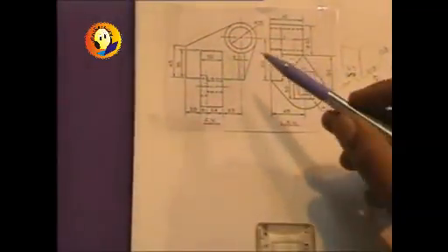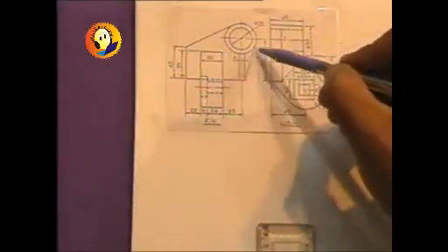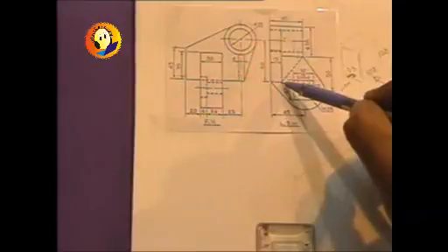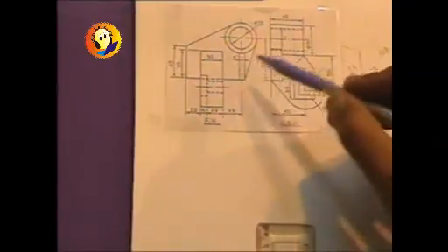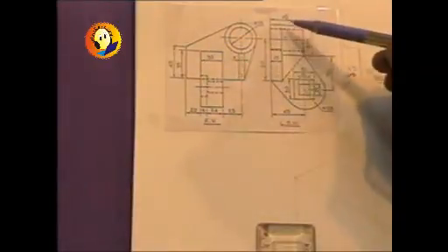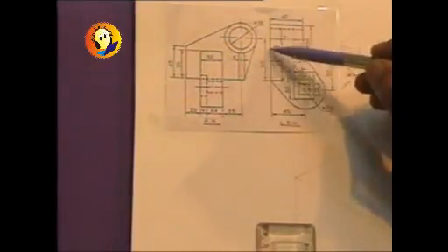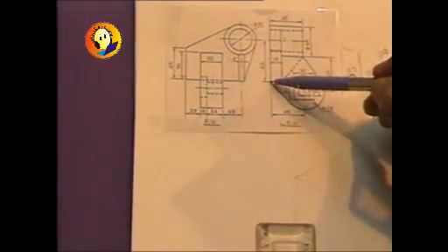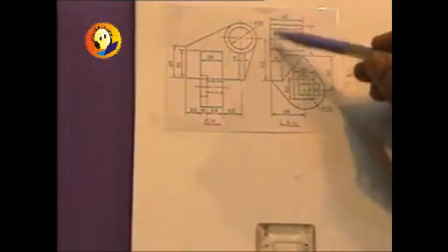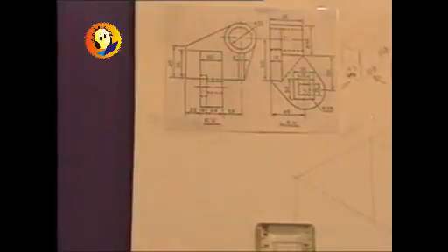So I have drawn the cylinder's box as if it is enclosed in a box. Now I am planning to draw this box which is of 15, and I can straight away just mark the rectangle. I will have to simply find out what is its distance from top, and you can find that this distance center to the bottom of that particular plate is 60 and the radius is 25. So it is in all 85 from top.